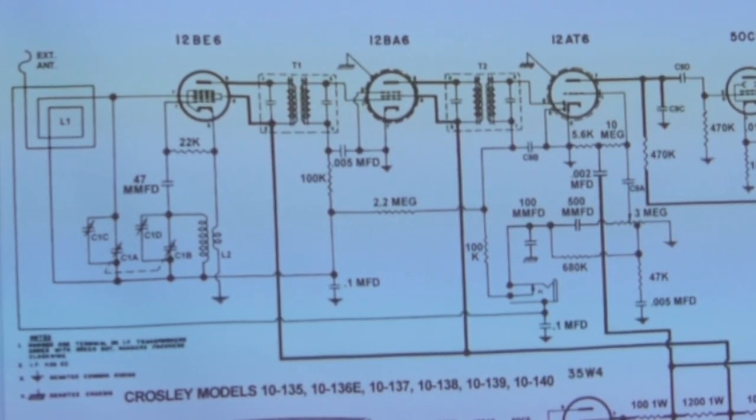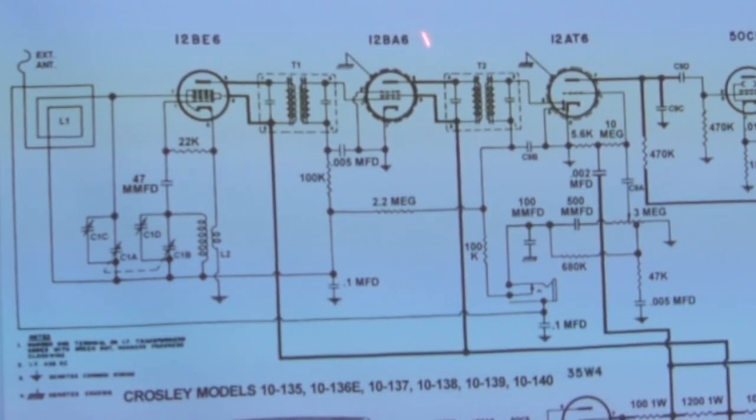The interesting thing about it is that you can't do anything about a weak radio signal with an AVC circuit, because you just don't have enough signal in the first place to deal with. So it's mainly beneficial when you have a strong local signal. A strong local radio signal may be as high as 100 microvolts coming into the antenna. Like if you get 630 on your dial or something, like a very powerful AM signal is coming in. And the AVC works to attenuate that very, very strong signal. And then it also, in variations of that signal, tends to even out the amount of maximum and minimum associated with the audio variations on that signal. So that's what the automatic gain control or automatic volume control does.